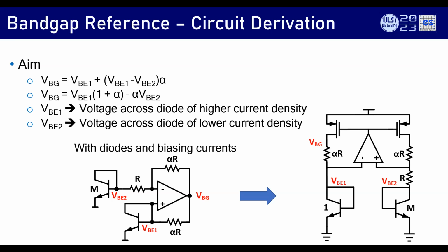Yes, I'll talk about that when I show you a circuit of how to bias the operational amplifier. In order to answer you, you take this current and mirror it back into the operational amplifier. So that is the bias current. There's nothing else available, only VDD. You take the same current and pump it back into the operational amplifier. The advantage is that all the VGS on the operational amplifier track because it has the same current, and that also helps give a low systematic offset. I will cover that also.